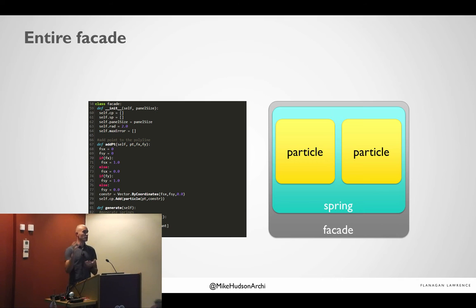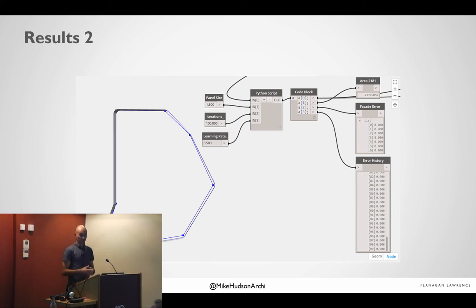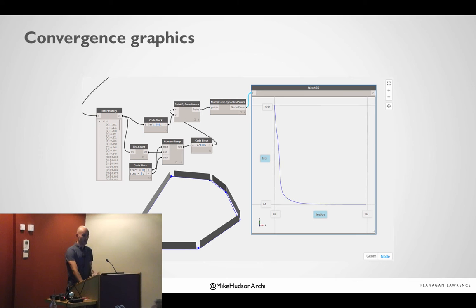So you can't do that by hand. It just becomes too complicated because you're just chasing your own tail forever. So we actually found, the first time we ran this, that there was no convergence. We couldn't get a solution because the learning rates that we defined were not incrementally large enough. We weren't being brave enough to try and explore different geometries, different setting out of these points. So the great thing about iterative programming is that you just tweak some numbers and tell the computer to go away and do all the hard work for you again. We increased the learning rates, increased the number of iterations, and then we got convergence.